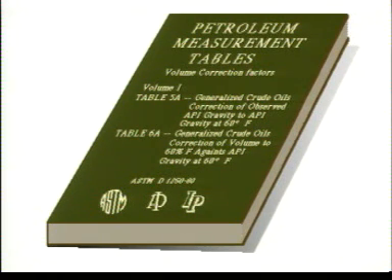To calculate weight of cargo, the oil industry mainly uses API gravity at 60 degrees Fahrenheit, or alternatively, density at 15 degrees centigrade as standard units of measurement. The loading orders for this cargo were given as API at 60 degrees Fahrenheit, so use this unit and long tons while working with this cargo.